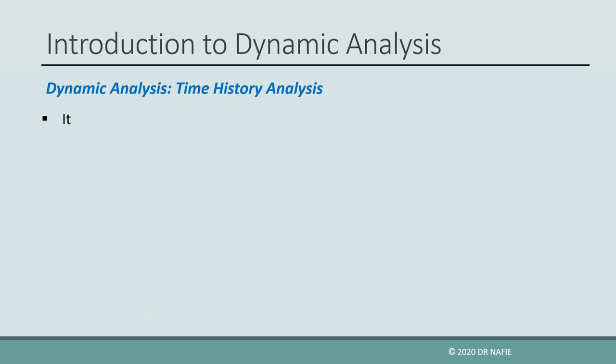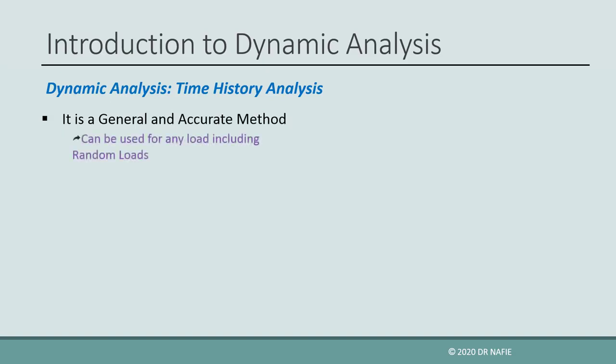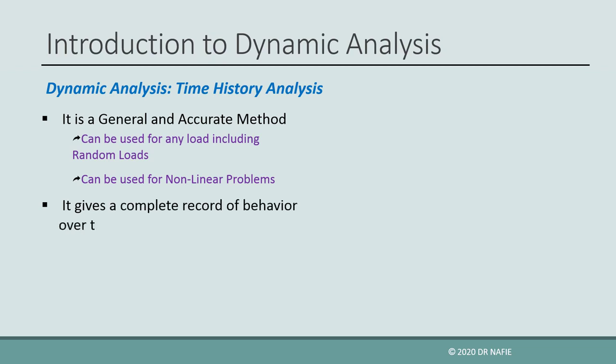The time history analysis is a general and accurate method that can be used for any loading condition and can be used for nonlinear problems. It also gives a complete record of the behavior of the structure with time, therefore it is called time history. However, it is time-consuming and can be very slow for large problems.